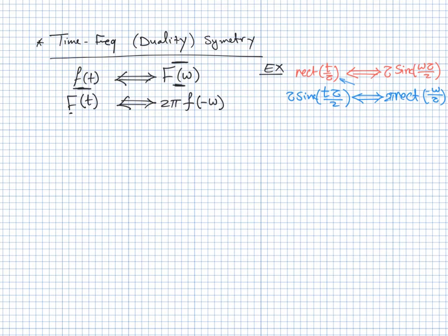Okay. So this allows you, if you know the Fourier transform of something, right, you can figure also the Fourier transform of its Fourier transform representation, right? Because this is the Fourier transform of this, right? Now this, using the duality, I was also able to figure out the Fourier transform if it was a time domain function, right? So this means that typically the table that you will get for famous Fourier transforms, you can also look at the frequency domain ones and think of them as being time domain, and using the duality you can get the frequency domain from the other column, right? So as if the table is being doubled, right?